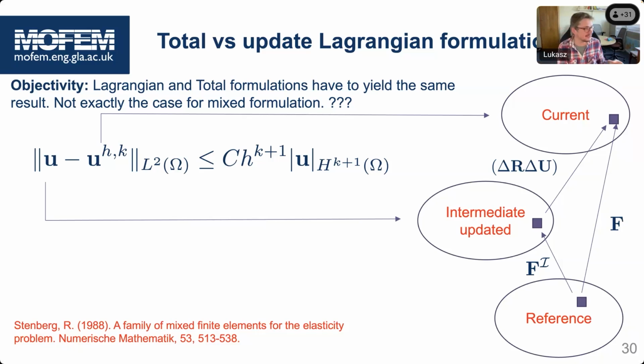That is a very interesting avenue, but it will not always work. The reason why is that these C1 continuous methods do not always work with large deformations, because once you project L2 space on H1, for high polynomial orders you can end up in a situation where the Jacobian locally becomes negative, and that causes a series of problems.